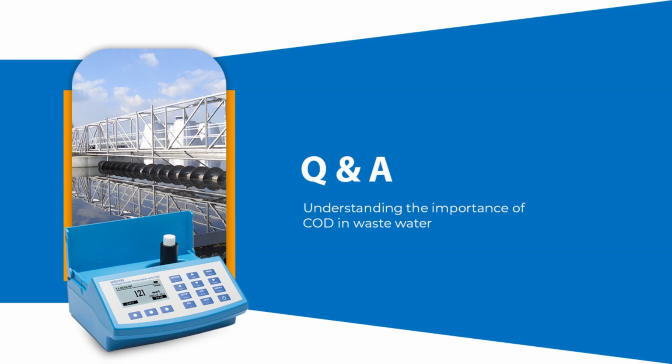Can you please explain the BOD measurements using the HANNA dissolved oxygen meter? Okay, in this we have the HI 98193. This is a DO meter, and it is also used for BOD measurements. You first have to take a DO reading on the first day, and after that you can take the BOD reading on the fifth day.